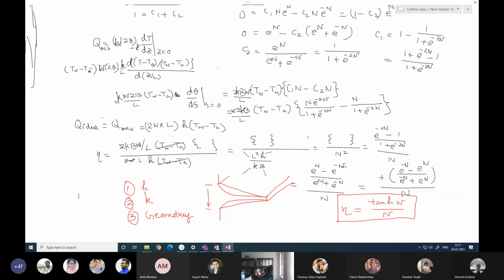To increase the heat dissipation from a 3 centimeter OD pipe, circumferential fins made of aluminium were soldered to the outer surface. The fins are 0.1 centimeter thick and have an outer diameter of 6 centimeter. If the tube surface temperature is 100 degrees centigrade and the ambient temperature is 25 degrees centigrade, and the heat transfer coefficient between the fin and the environment is 65 watt per meter square Kelvin, calculate the rate of heat loss from the fin.